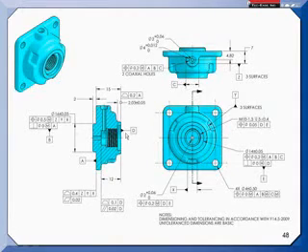Okay, I was pointing out that datum feature D is located with respect to A, so it's controlled. So I'm not following the question, I guess. Oh, you know what, Don, I'm sorry. Now that I see that the datum feature D symbol is not off of that profile to A feature control frame, to me, it looked like it was just standalone. So I guess basically my question is, do we always want to have subsequent datum features controlled back to the primary in sequence, or can you just allow manufacturing tolerances to dictate how features are controlled to each other?